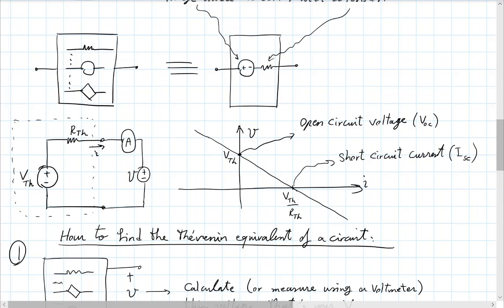This entirely defines the Thevenin equivalent of the circuit, right? You have something in the box, and from the outside, it looks like this. We saw that you can construct this with, indeed, one voltage source in series with a resistor. Can you also try to construct this with a resistor and a current source?